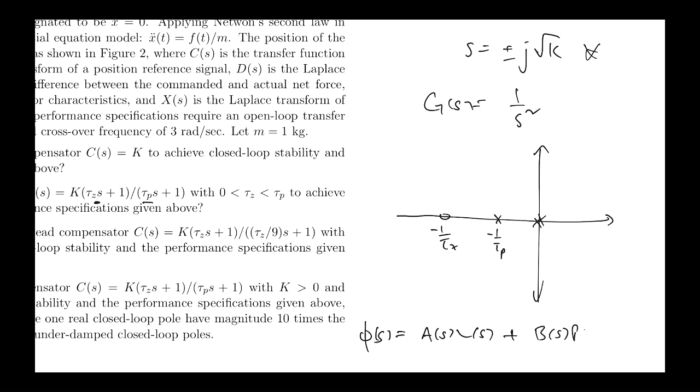Okay. So the degree of the characteristic polynomial is really determined by this product here, because we start with a proper controller and plant transfer function, right? And the order of this will be the number of open loop poles, right? Because the zeros of A are the plant poles and the zeros of L are the controller poles, okay?